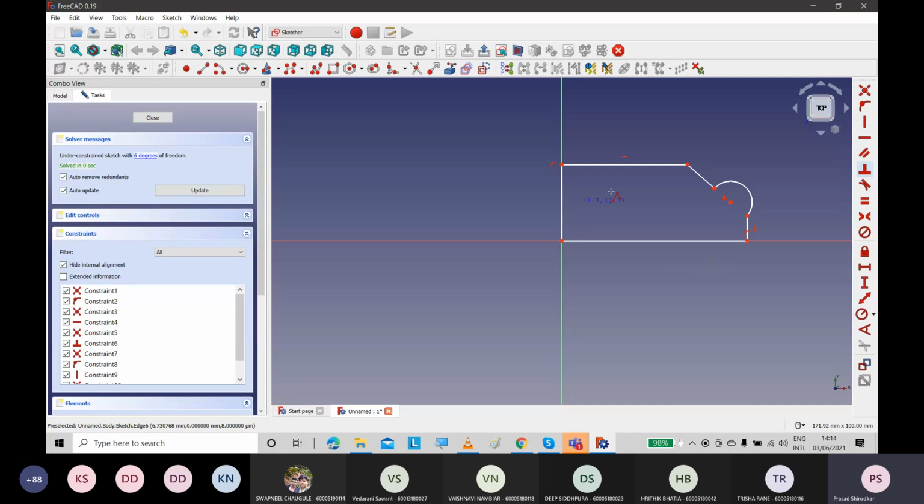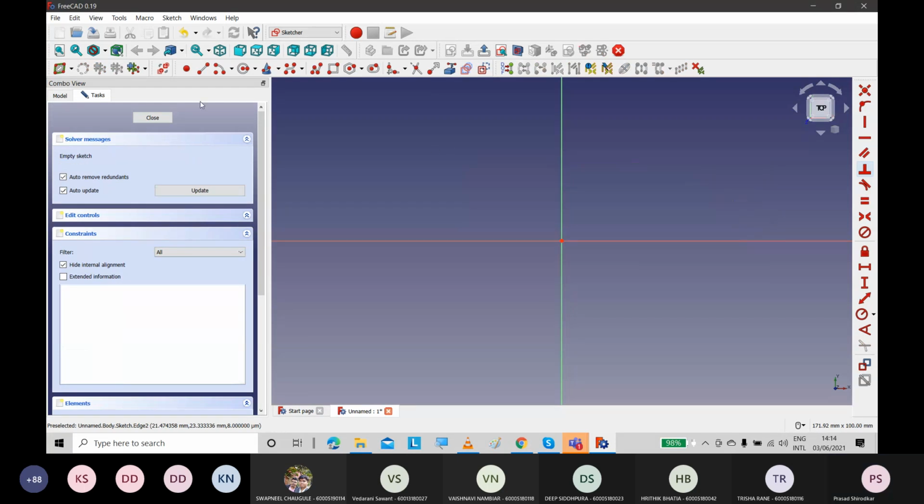Then you can give the dimensions on this. So let me just do a different one. Go to the polyline. Select one. Here, vertical. Then change it. Press M. Change it to arc. Again press M till you get the vertical line, and then just close it.